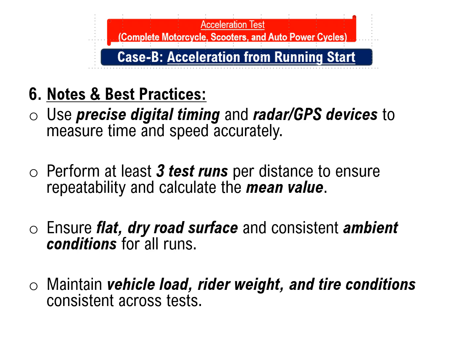Ensure flat, dry surface and consistent ambient conditions for all the runs for the purpose of comparison. Maintain vehicle load, rider weight, and tire conditions consistent across all the tests.